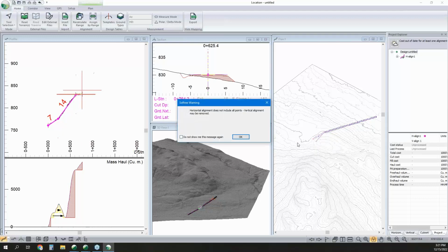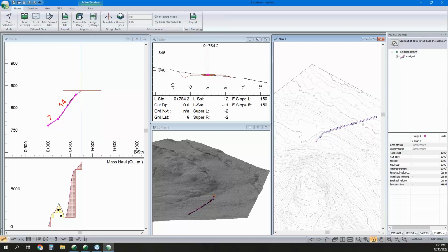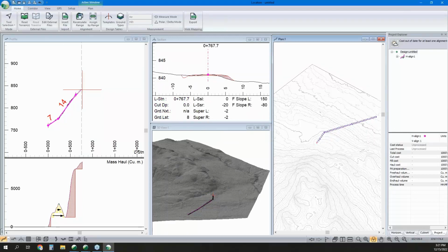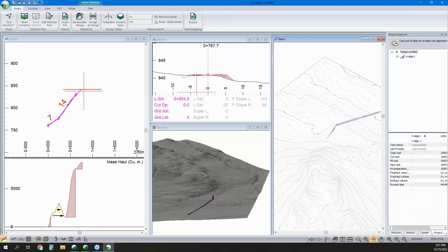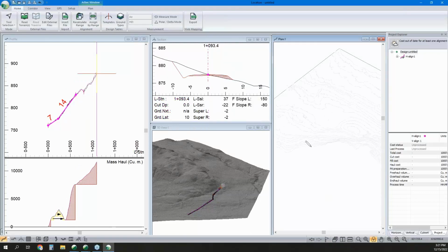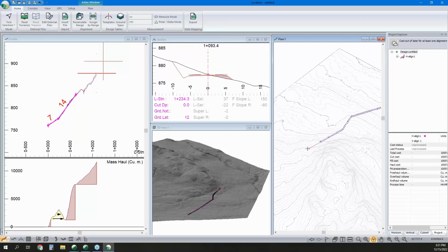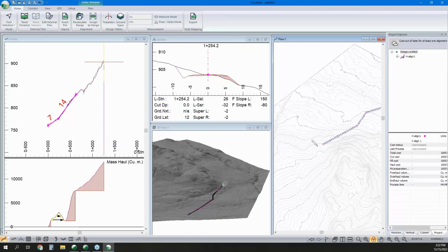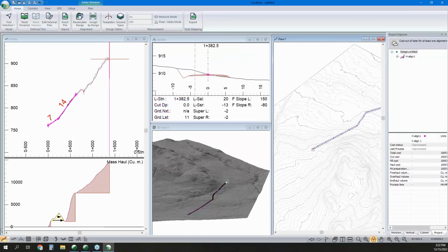I'm going to move this point, and where I'd like to go to is up on that ridge. So I'm going to move that point, and I'm going to try and keep climbing without exceeding my max grade. So it's a 3D problem. We won't think of just the horizontal or just the vertical. And let's go there.